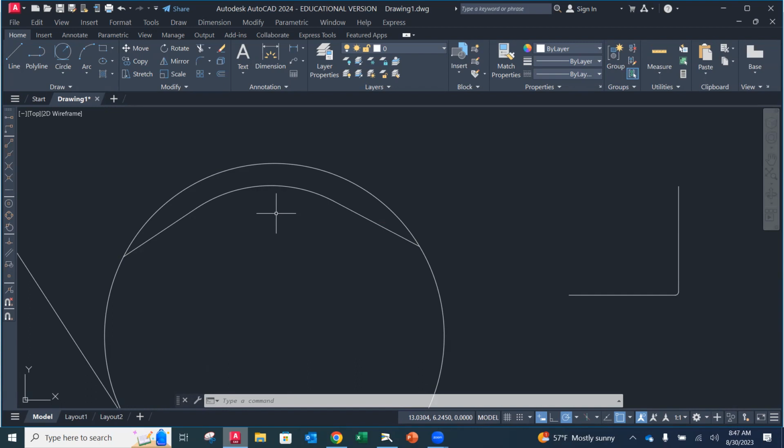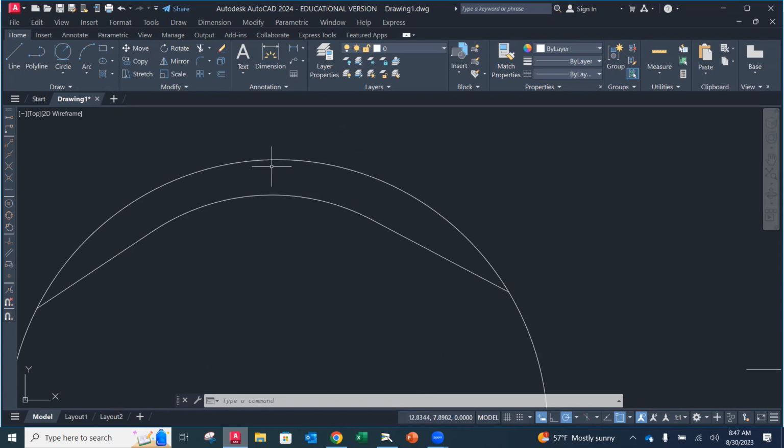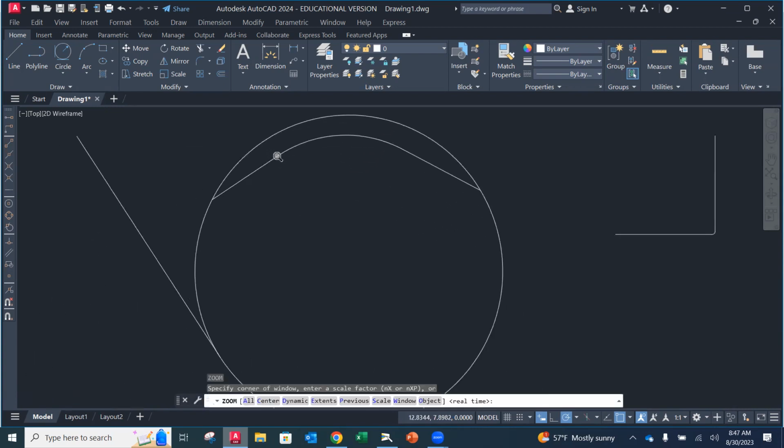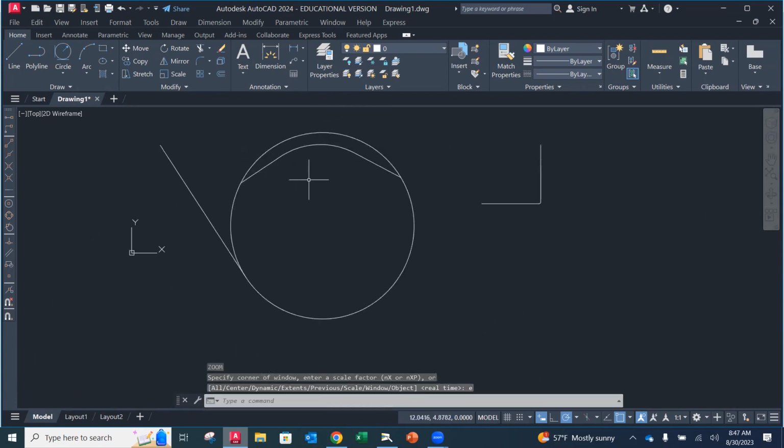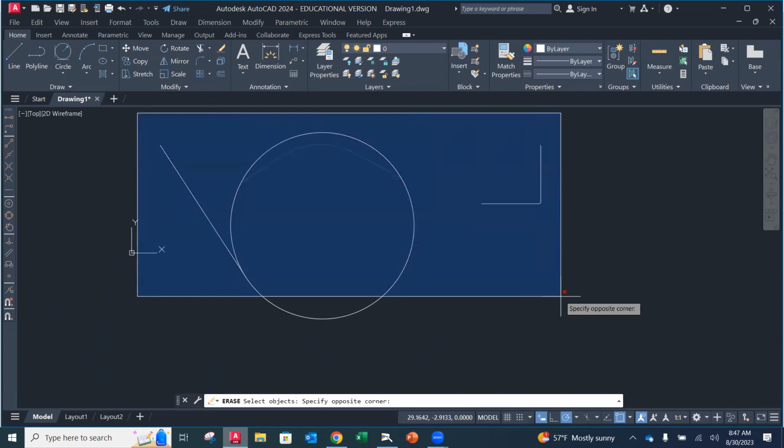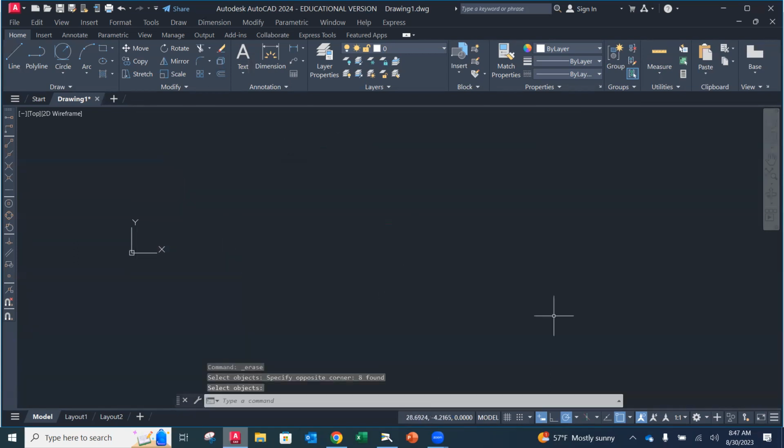All right. So we're ready to actually do the gasket tutorial. What I'm going to do now is a zoom enter, extents enter, get everything on my screen, roll the wheel towards myself so I can see it, and I'm simply going to erase everything that's here. Enter.